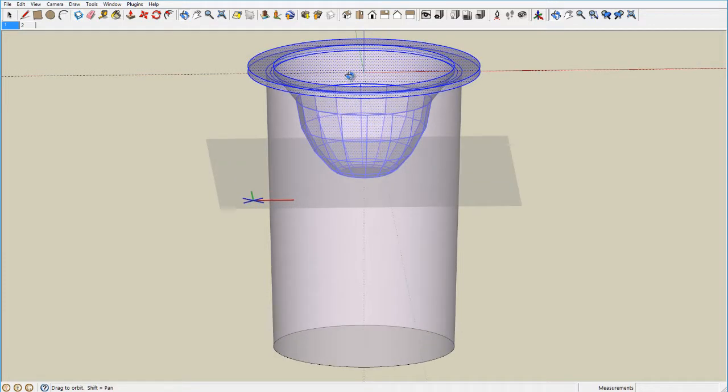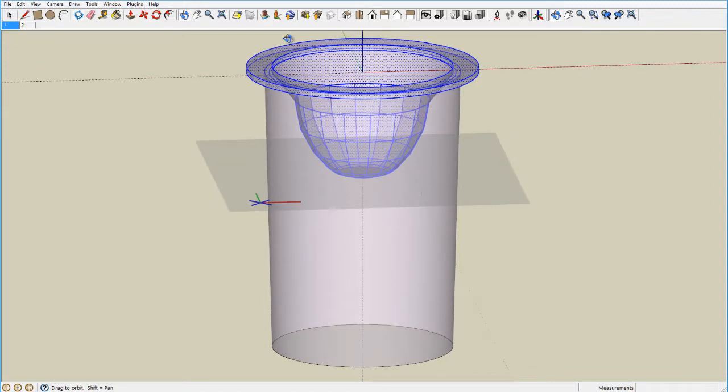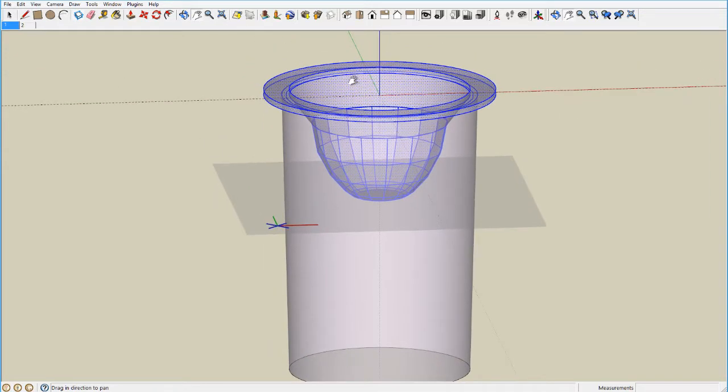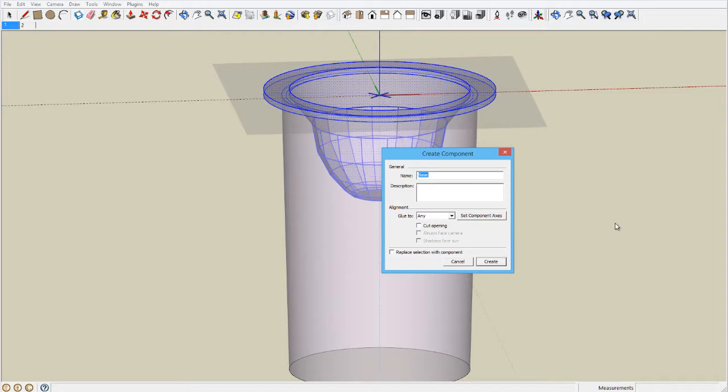move the view so that we can see our axes more clearly, and now clicking on and seeing the highlight as origin, which is exactly where it needs to be, and then in SketchUp to set the origin you select the origin point, then you select anywhere along the red axis and then anywhere along the green axis, and there we are, it's set.